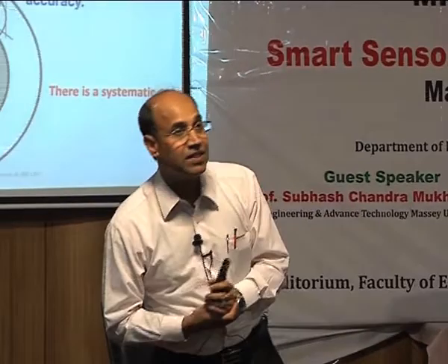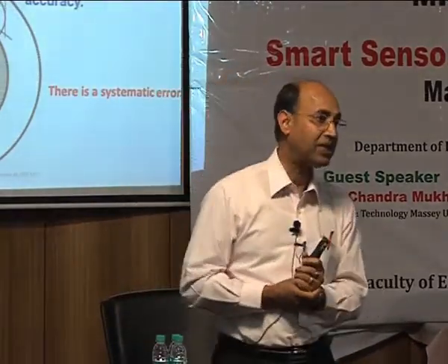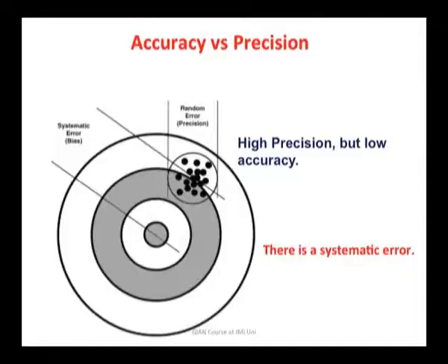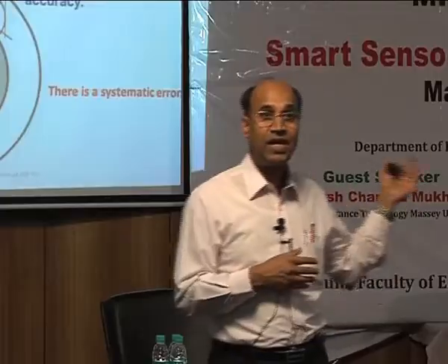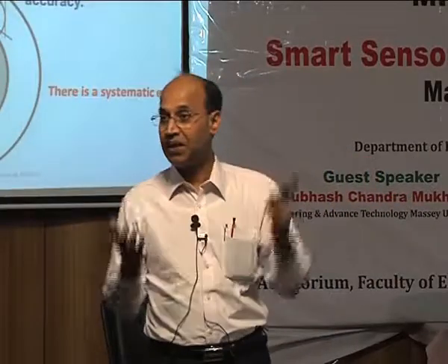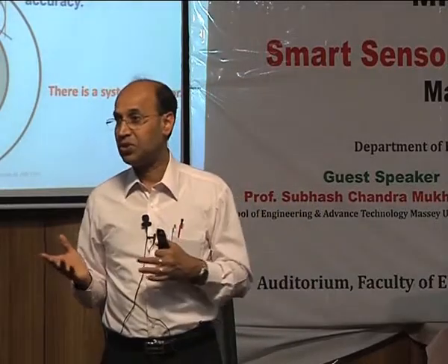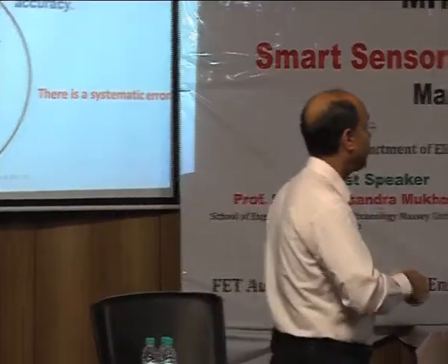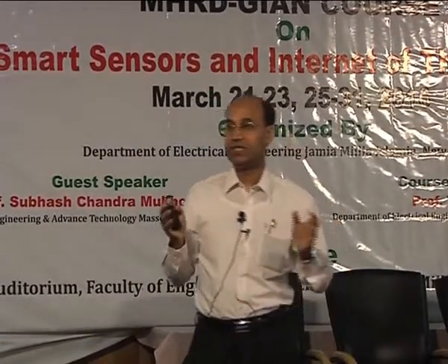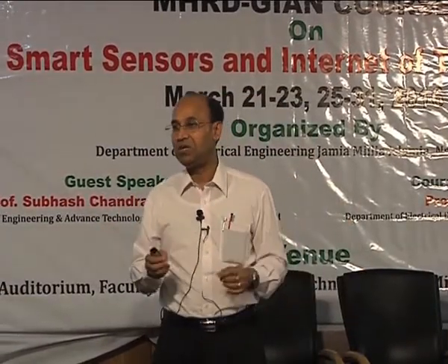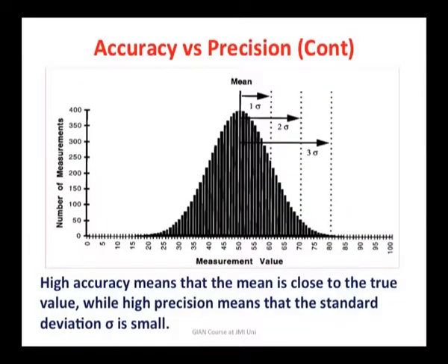In a magnetic sensor, the magnetic bias is very, very important. And if you bias in such a way that you really don't know how much you actually biased, it can give you that type of situation, where the effect of the bias is beyond your control. Okay? So you always get the same result, and you are 100% sure that no, this is not correct, something is going wrong, but you don't know where. Okay? So you end up with this type of problem.